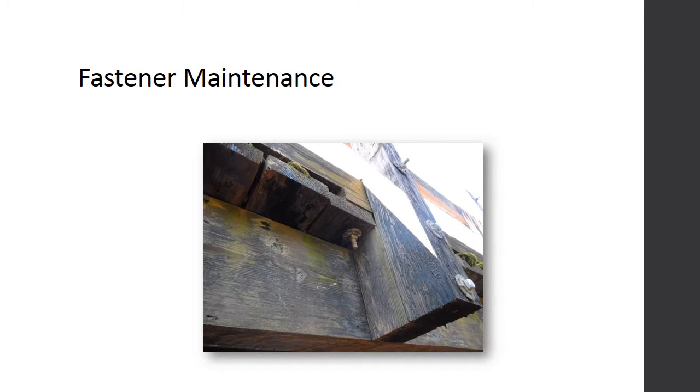The condition of all structural fasteners should be checked for corrosion and tightness. Fasteners should be retightened to a snug tight condition if deemed loose. Where significant corrosion is present, fasteners should be replaced altogether.